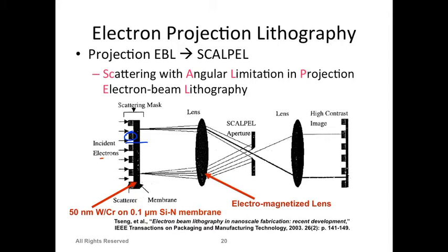Can you make this kind of a wafer? Yes, we can use maybe TMH. We can take a wafer, right? We can deposit silicon nitride on both sides, right? And then we open a window on one side, do TMH. It will etch all the way through the silicon until it reaches the other side, where you have the opening.